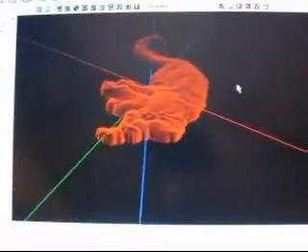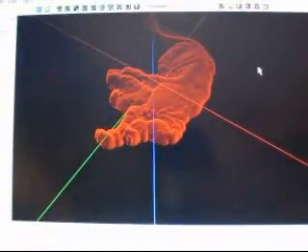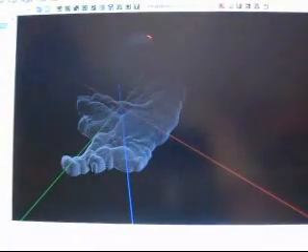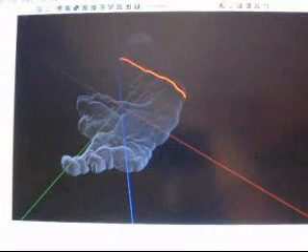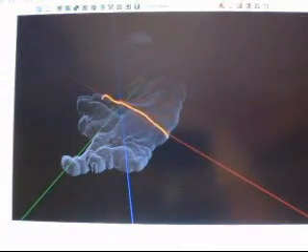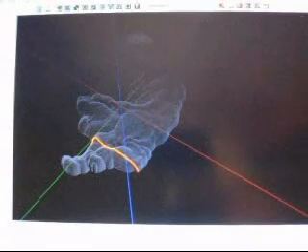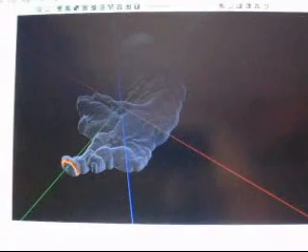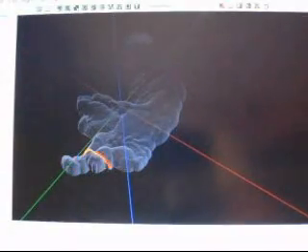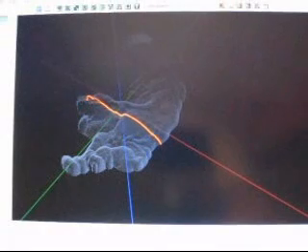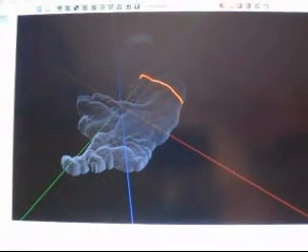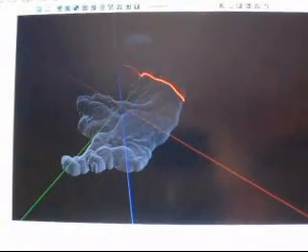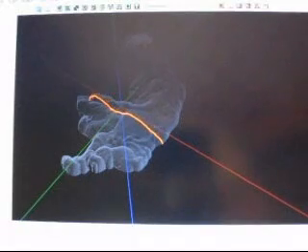So we'll just view it like that for a minute, and now I could just run through with my arrow button through the list of those polylines. As you can see, there's a lot fewer entities because they've all been converted to polylines. I'm just pressing the arrow key to step through all of that. So that's the manner in which we want to scan the tool path.